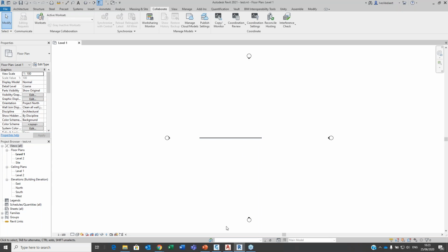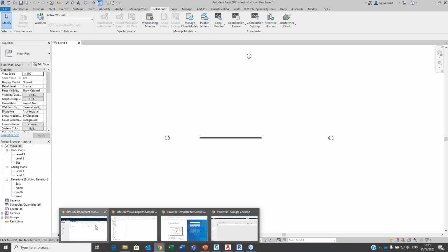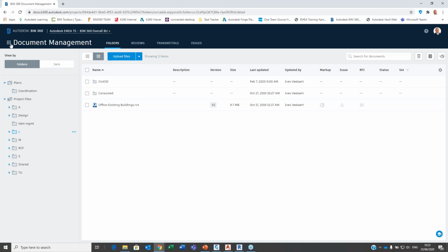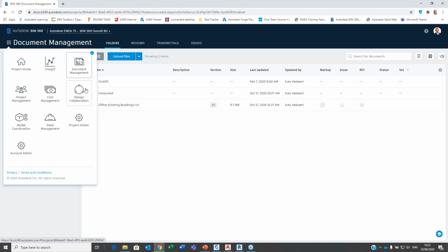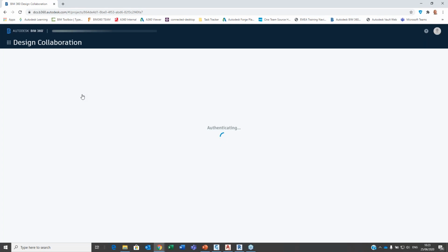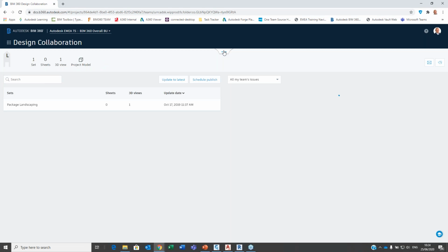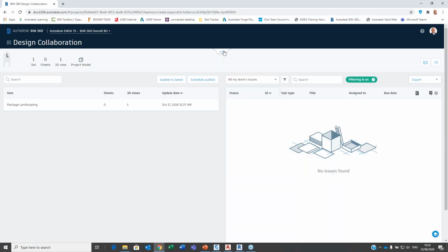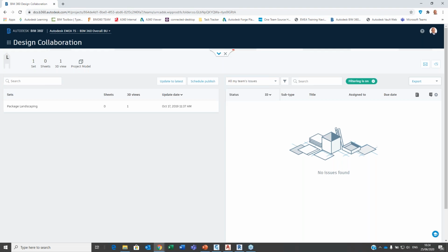So essentially what I've just done here without the work sets, that's BIM 360 Docs actually. That's a connection to BIM 360 Docs and having a Revit entitlement. When I go into BIM 360 Docs here and I swap over to design collaboration, that's that cloud module that I was talking about where we can look at the packages and communicating between disciplines. That's where you need a BIM 360 design entitlement as well. So if it's just the smaller company who's going to authorize you as the bigger company to say, yeah, you can take charge of the packages, the only thing they need is Revit, connection to the cloud, that's it, which essentially means a BIM 360 Docs entitlement, okay?